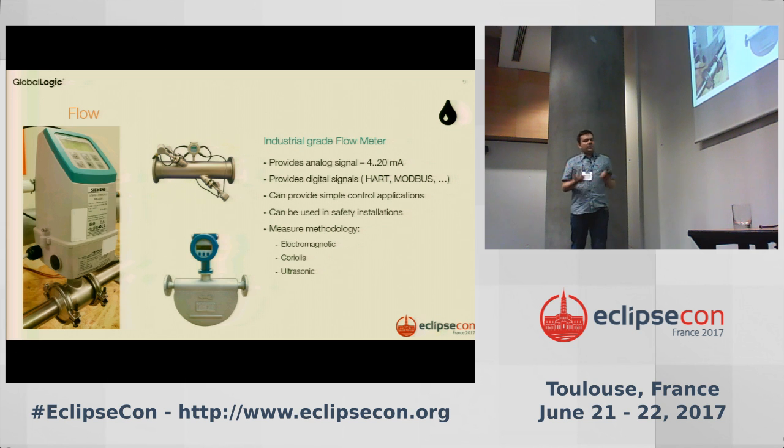The most common ones are electromagnetic, based on the change of the electromagnetic field during the flow of the medium, water for example, or another fluid. The field is changed, so it can be detected and changed into the volume flow. Next one is the Coriolis one.